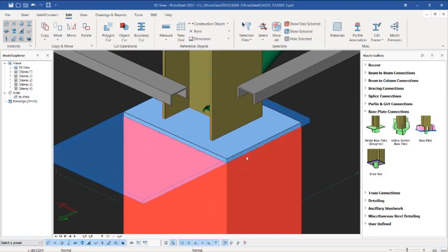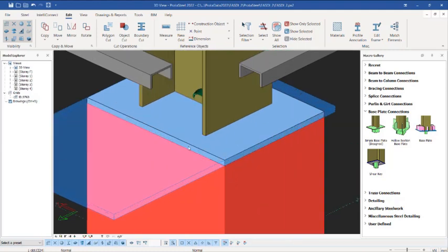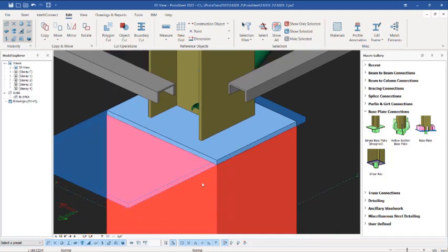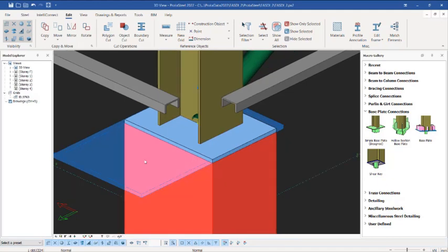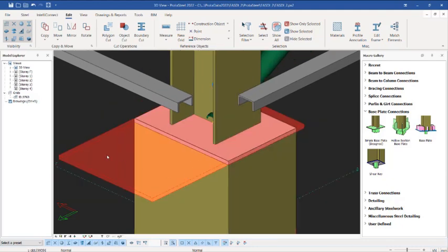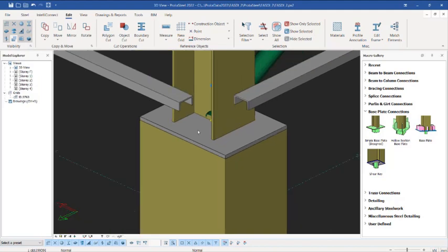All right, so with this now, if you carry out a clash check, you will notice that there will be nothing like a clash between the reinforced concrete column and the plate, because we have cut the part that is clashing out. All right, so this is an auxiliary file, these cut symbols, so you can also remove it. If you want to remove it, you come to these provisions, where you have this one. Click on it to remove that. So this is the plate itself.